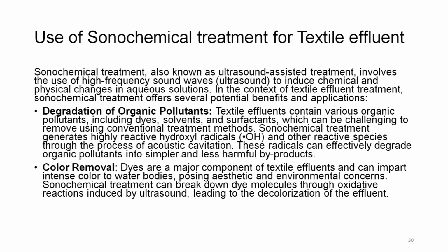Degradation of organic pollutants. Textile effluent contains various organic pollutants including dyes, solvents and surfactants, which can be challenging to remove using conventional treatment methods. Sonochemical treatment generates highly reactive hydroxyl radicals, OH dot, and other reactive species through the process of acoustic cavitation. These radicals effectively degrade the organic pollutants into simpler and less harmful byproducts.